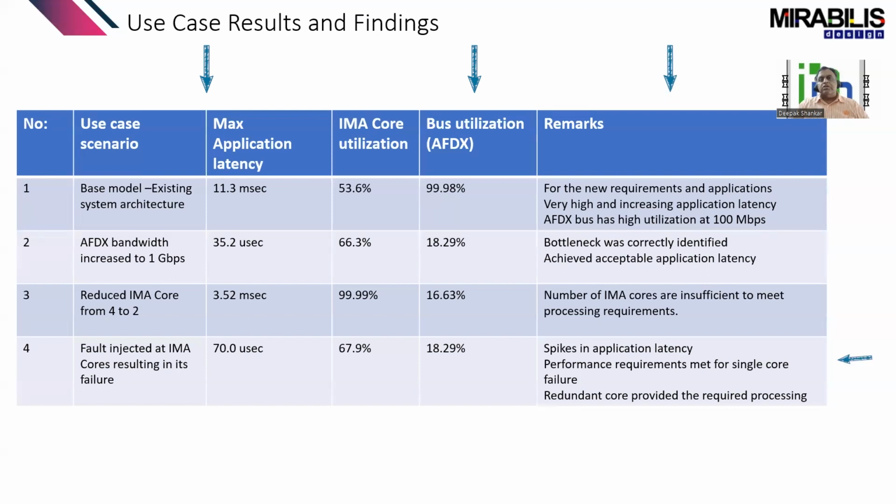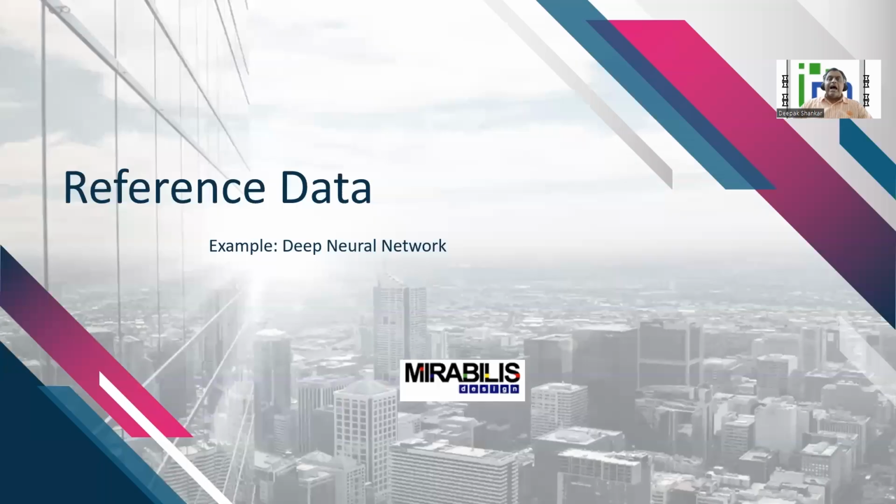You can look at what's the utilization of the bus or the processor, and then use that to make a decision as to how to size each of these subcomponents, which eventually are going to go on individual dies, be able to size those dies as well. So even before you transition from, say, a board or a multi-board solution to a single chip, is it possible that you can reduce some of the requirements on the system, so that way you're not creating a very, very complex chip or a chip that requires 7 nanometer when you could have done most of it in 28 nanometer.